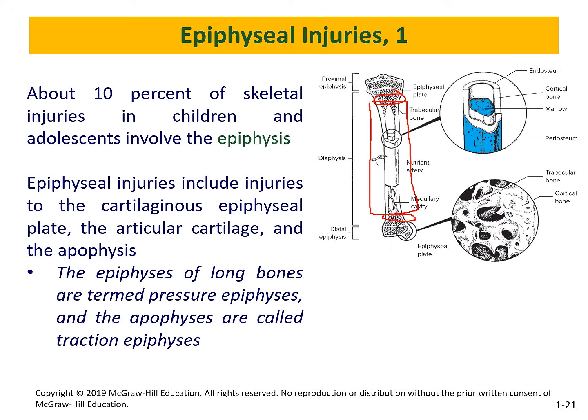What I care about is how we think about bone, correct? As an engineer, you need to understand the types of bone and the modes of failure. The reason why we learn this is for you to be able to design plates and screws. So if your bone is actually weak and you're putting in plates and screws that are very strong, you will have what Emily mentioned, the stress shielding, and then you make it an even worse problem. So the challenge with us is understanding the health of the bone so that when we put in plates and screws, we select the correct materials for them. Does it make sense?